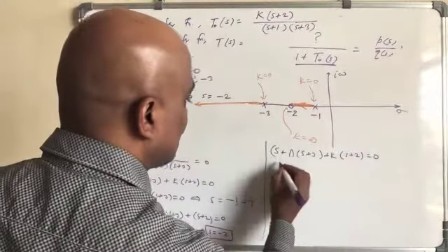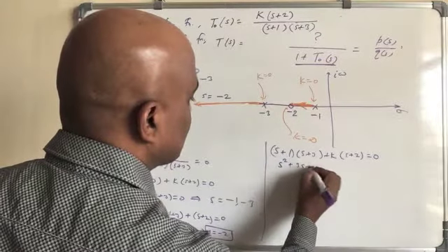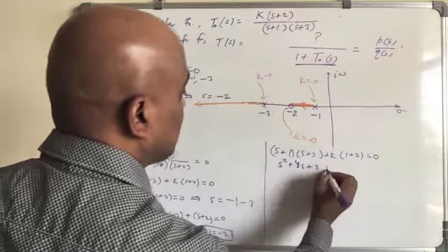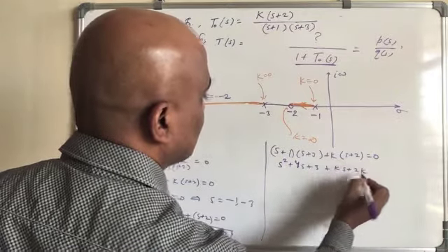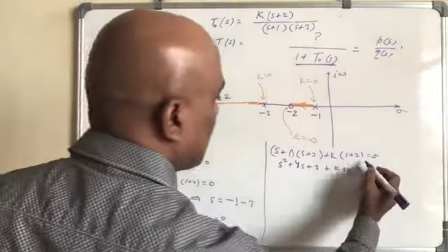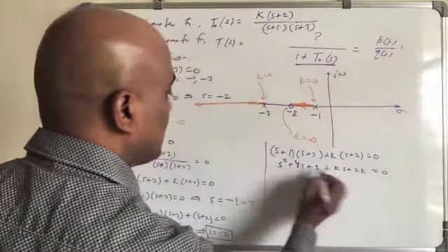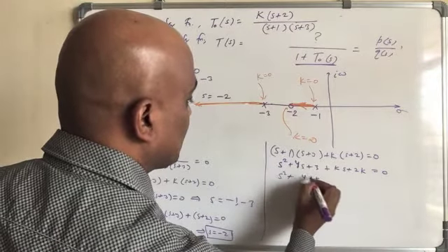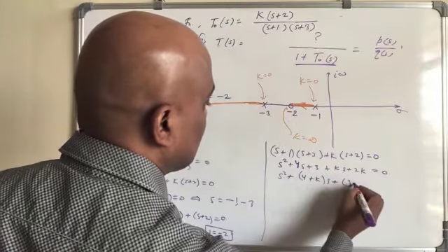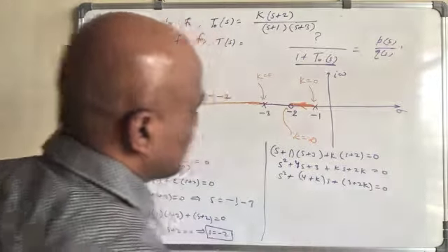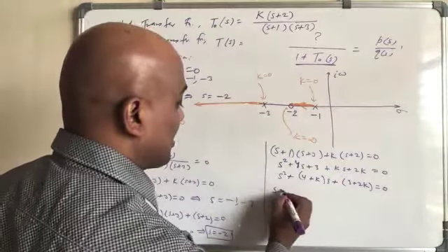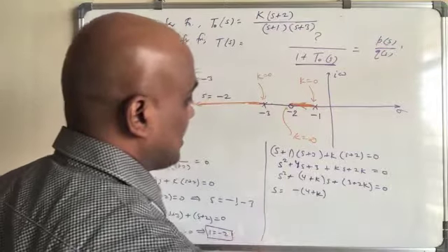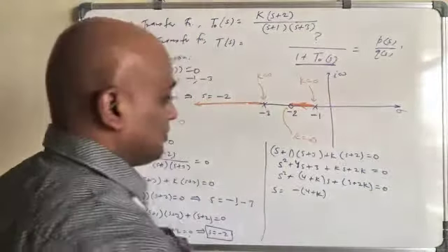We have to find out this one. So we have S square plus 4S plus 3 plus kS plus 2k equal to 0, and here you get S square plus (4 plus k)S plus (3 plus 2k) equal to 0, and from here you can find out S equal to minus (4 plus k)...